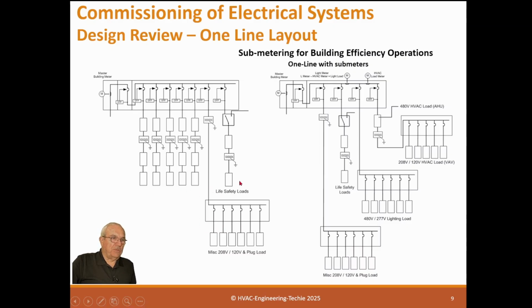And the reason is because of all the loads, the only one an operator can actually affect really is HVAC. How they manage the HVAC system, how they maintain it's really important for energy. But if that energy is buried with plug load and lighting load, then it becomes much, much more difficult to tell when you make a change or you make a correction if it actually did any good. So what we want is, instead of all these panels coming back to the SES, to have a distribution panel for each separate load.